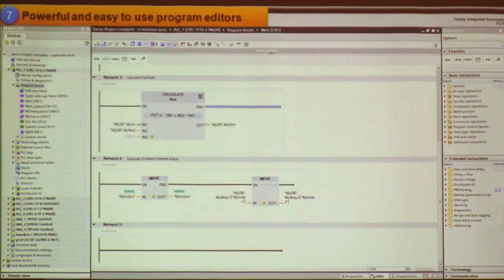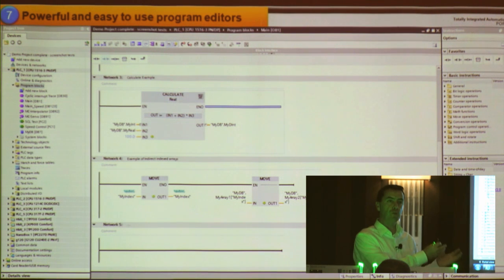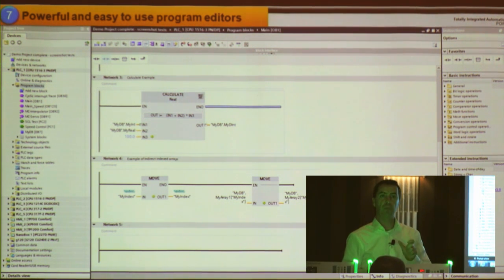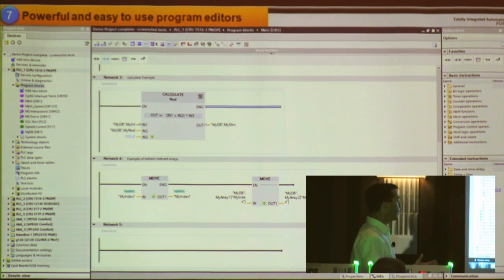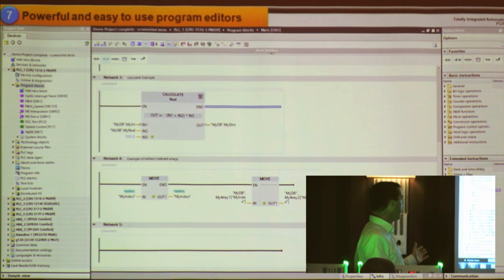Well then, very quickly, the quick overview. We have this with the 1200, but with the 1500 you now have a lot of new software features that the S7-1500 and 400 PLCs don't have. Some of these here: the calculate box, where you can just put in an instruction and type in an expression, and most importantly, the data type handling doesn't matter. Short int, real, double int, whatever you want, you can mix and match the data types to create your expression. Another important feature is indirect addressing in ladder, a variable index in an array. You don't need to go to a textual STL language to do that. It's all in ladder and FBD to do your indirect addressing or pointing. Those are some of the key features. We also have a 64 mega data block as well.